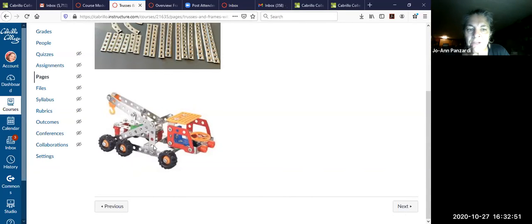Okay, so the difference between when you call something a two-force member or a three-force member or a four-force member, it depends on how many connections or forces are applied at the points. If the connections are all, or the forces are only at the ends, it's called a two-force member. If they're in the middle, they're considered a multi-force member. And in this case, it's a three-force member.